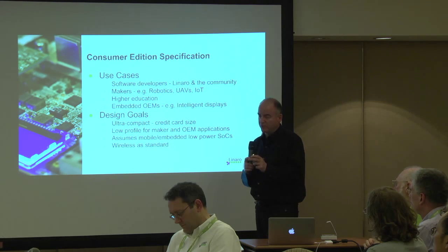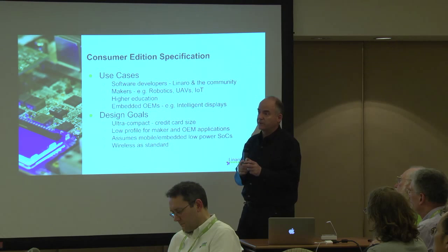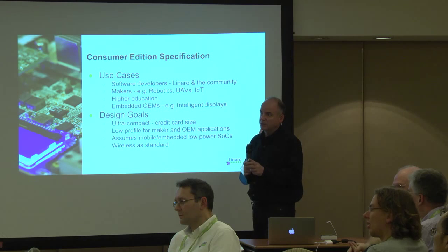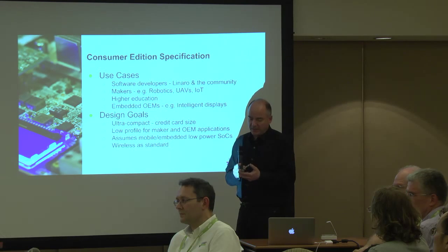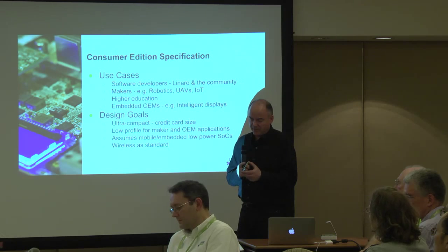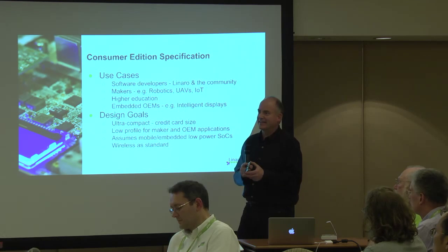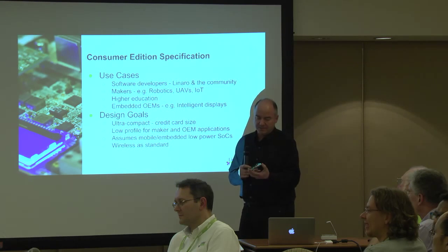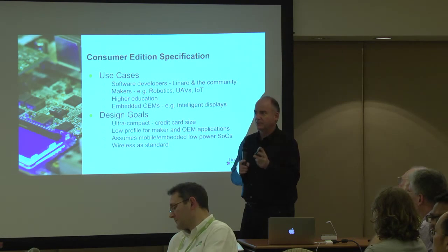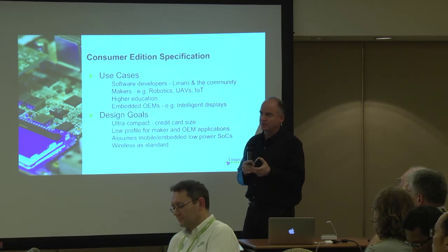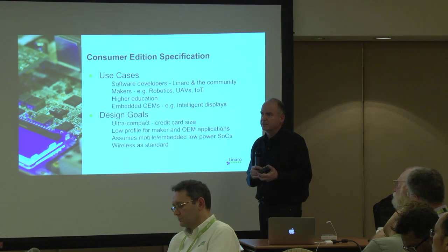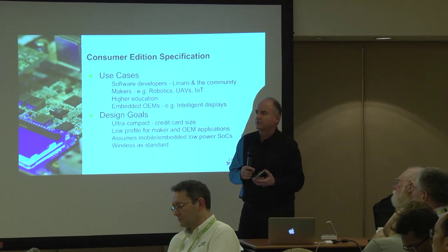We are using a pre-approved module for Wi-Fi and Bluetooth, which means that you don't have to go through full radio emission testing when you're doing the FCC. However, if you plug an external antenna on, then you theoretically are not approved anymore. So this uses a PCB antenna, but it also has the capability of putting an external antenna socket in, at which point it would not be approved. But typically on these boards, what we see nowadays is they are generally approved.